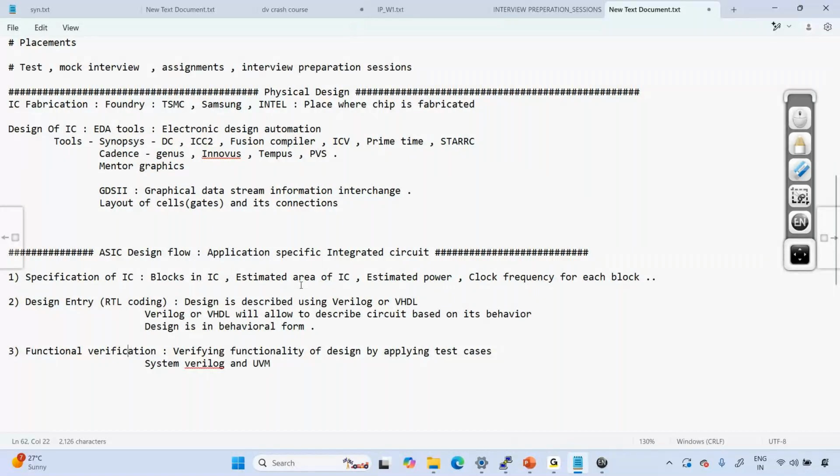Once the design is functionally verified, it goes to physical design, where they do timing and all these things. They may fail in physical design even after all these verifications. Yes, timing may fail, right? So from physical design to RTL, hand checking happens many times. I am having a large logic depth, I am failing in timing, I am seeing huge logic depth there. So please correct it. Again they will correct and send again. Hand checking happens many times.